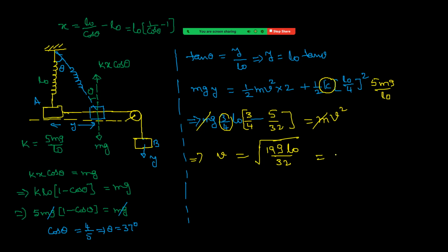We get approximately 1.72 meter per second. Okay. So here we have taken the condition of losing contact, that's why the force equation along. But for the second equation, we have to find speed. So we have taken conservation of mechanical energy, and the remaining is just the calculation part. So I hope you got clarity.